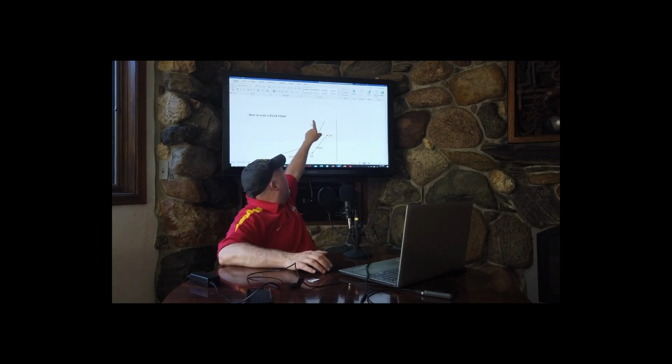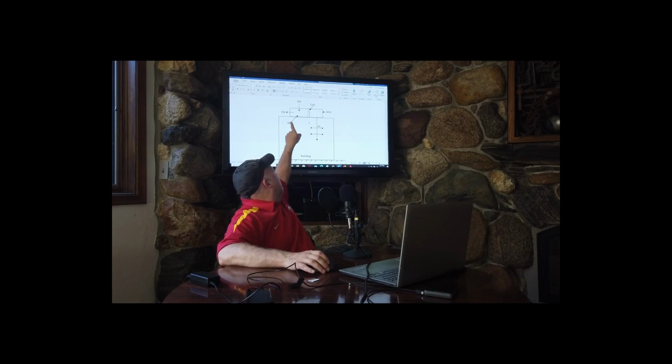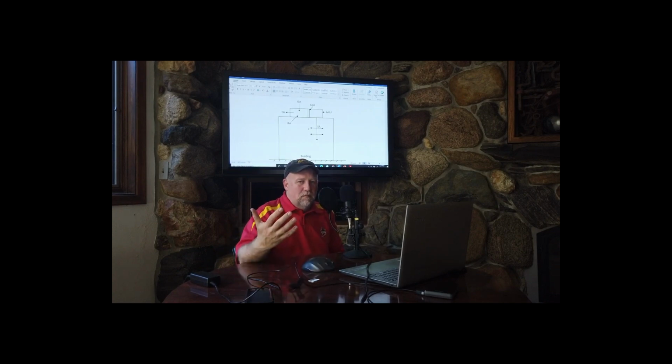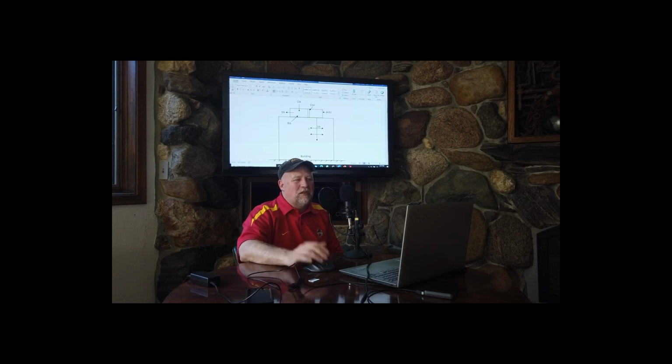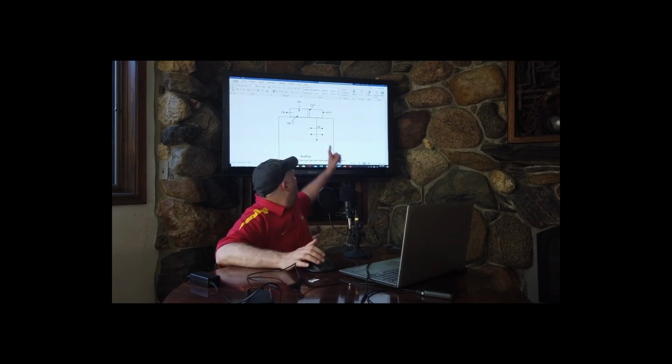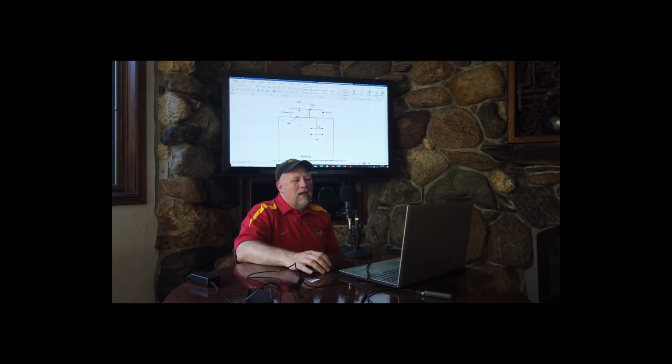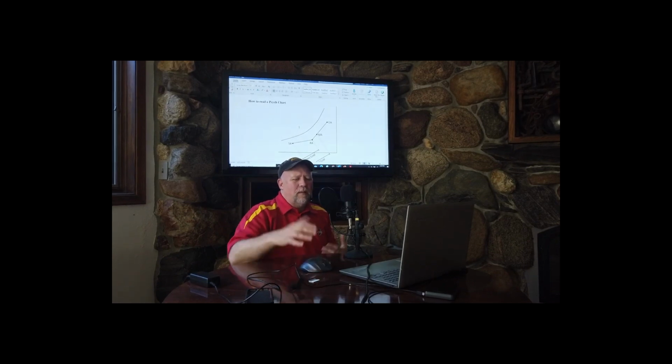Now, outside air. Let's go back to this picture. So that's the air that we dump into the room. The air that we return is the conditions that we want the space at. In other words, 72 degrees Fahrenheit, 50% relative humidity. Most of the time, those are the space conditions that we're going to use for this class. Outside air. So we're going to exhaust some of that air and bring in some fresh air into the air handler. Why do we need fresh air? Right? What's the importance of that?